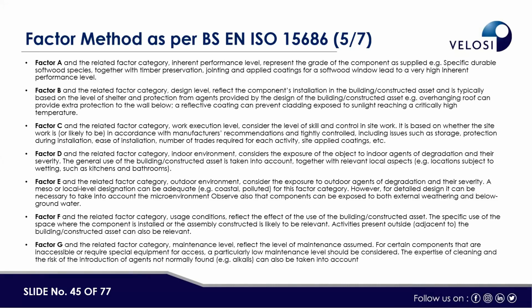Factor B would be for the design level, which reflects the component's installation in the building or constructed asset, and it is typically based on the level of shelter and protection from agents provided by the design of the building. Then factor C is for work execution level: how the execution of work has been done, and what the quality of the work is.